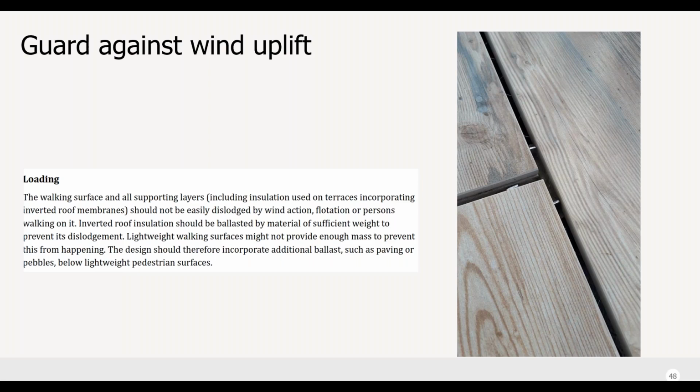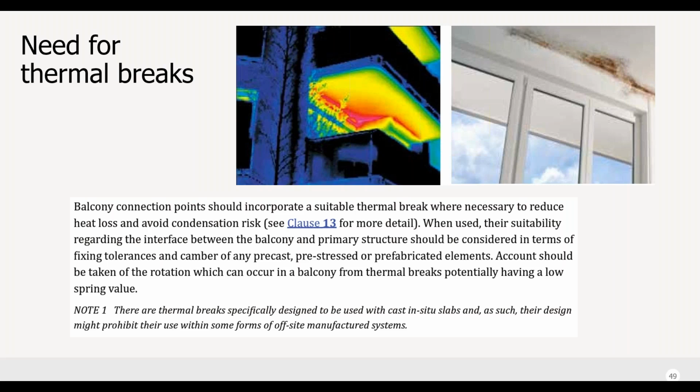The next slide touches on thermal breaks and the efficacy of those. As many would know, thermal breaks serve two specific purposes. One is to minimise heat loss, and their standards are being raised all the time for what is needed, especially with the advent of passive house and other high standards, but also to minimise the risk of condensation forming within the building.